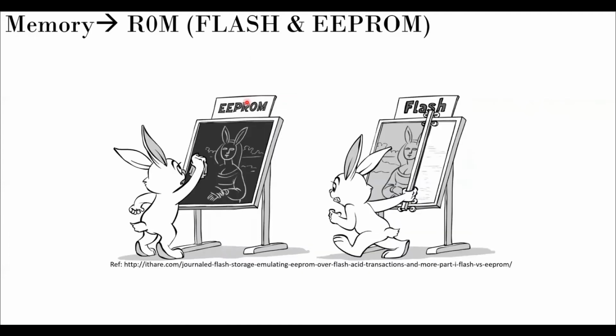Okay, and this is that chart. This is really attractive for me because this really highlights the difference between EEPROM and flash. And sometimes pictorial representations are much easier for you. Right? So this is how it looks. So EEPROM, as I said, erases byte by byte. So it is something like you have a duster in your hand and you're cleaning the board. It takes so much time. So if we had something like this arrangement, smart, right? You can clear it as a block or a wall. Okay, so that is the main difference.